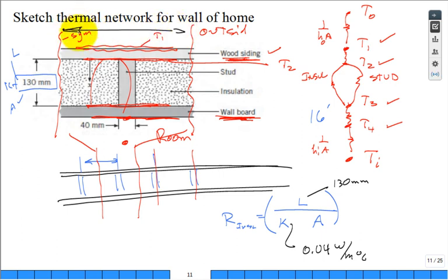And so if I said this is for the insulation, let's say this is, I don't know, let's pick 500 millimeters. This area is going to be 500 millimeters minus the 40 millimeters. Why am I subtracting 40 millimeters? Because it's not going through this one. You know what I mean? It's not going through the stud. I'm just doing the insulation.